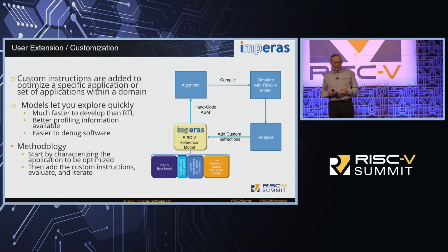When it comes to custom instructions, we have our basic model that is delivered, which has the base RISC-V stuff in it, and whatever the IP vendor might have in it. But our technology and methodology allows you to add custom instructions, custom interrupts, custom state, and communication. So you can change the model. When we have technology simulated, obviously, we have technology to analyze it in terms of profiling.